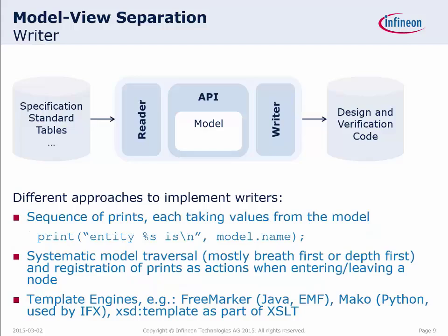On the writer side, you can iterate over your, let's say, field API model, register by register. For example, if you generate a firmware header file with definitions, register names and offsets, you would just use a print statement into a file or on the console, however you want to generate and output the data.